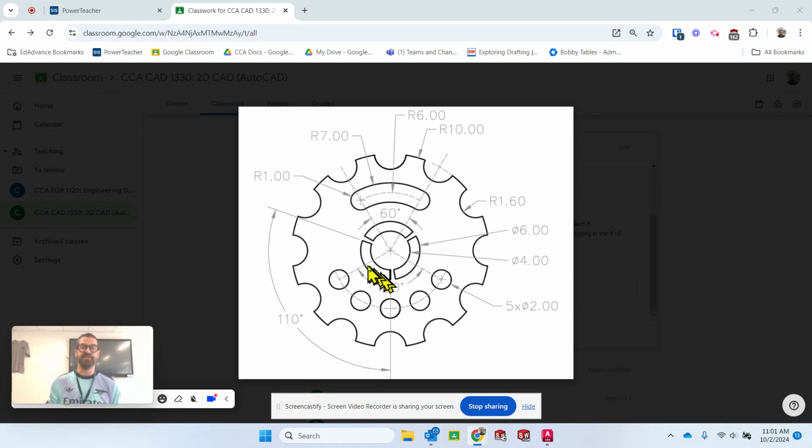I then made these 3 things right here, which was a line straight here and a line that went out along a construction line that I drew. And then I repeated that using the polar array. I said I wanted to go 360 degrees around the center point, and I want 3 of them. And so then it made those 3.